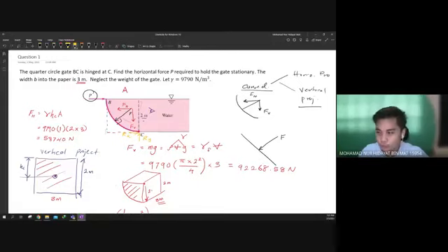So we have additional two forces. So what to do? We can cancel this force by putting the summation of moment at point C. Then we can cancel out reaction force at point C. So far are you clear about this?